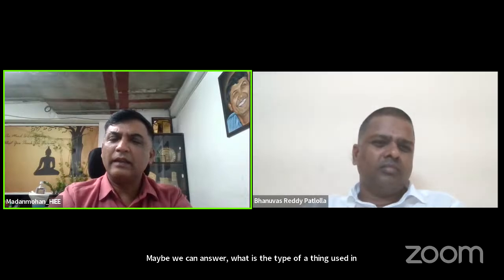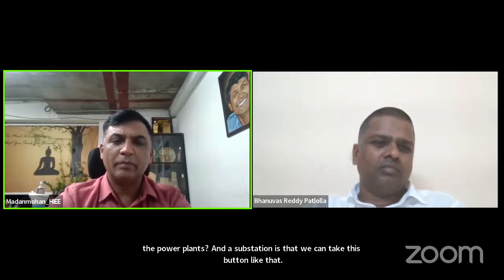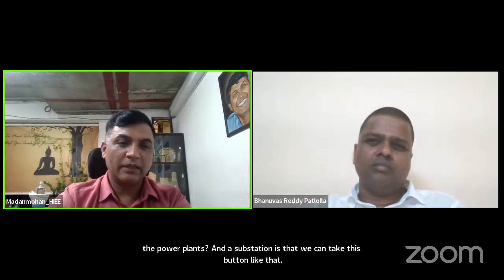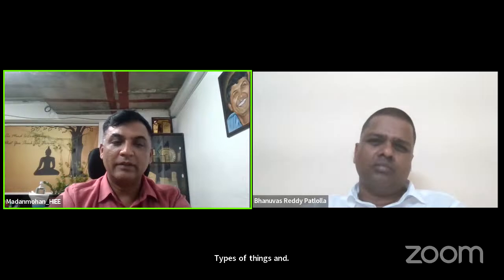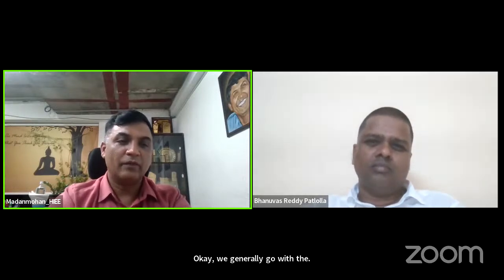For higher rating substations, generally we provide an earth mat to drain the leakage currents effectively into the ground. The earthing types are as per IEEE 80. We generally go with the earth mat design for the substation to drain the fault currents.